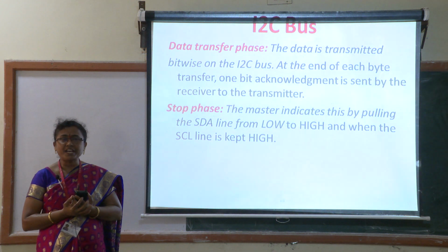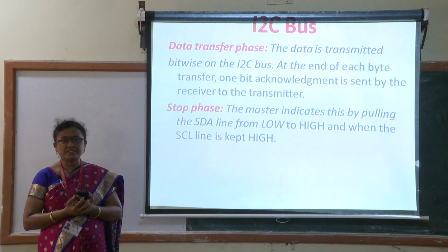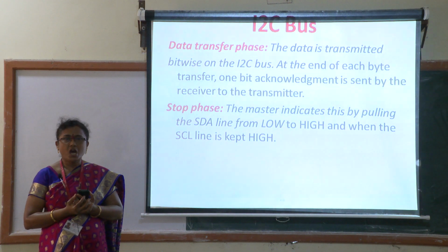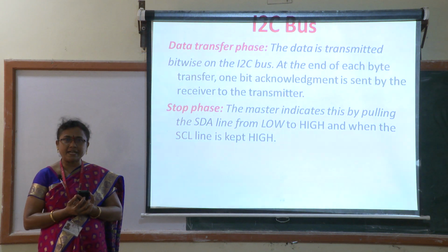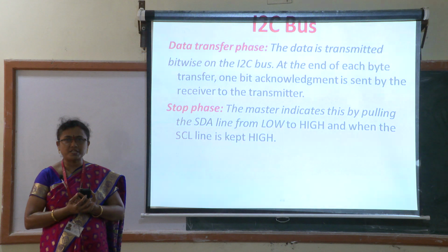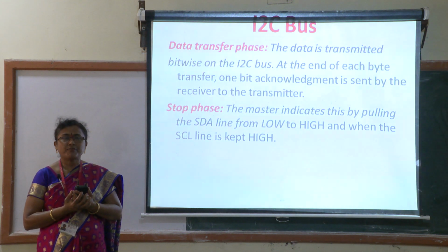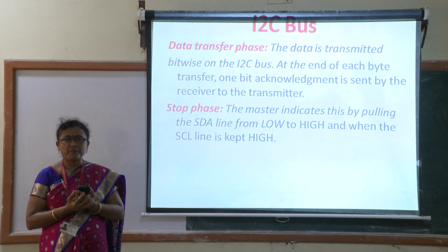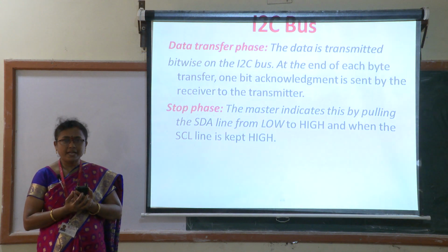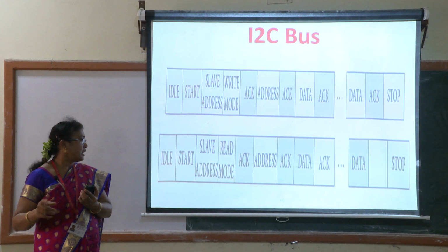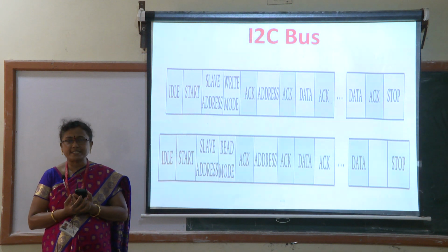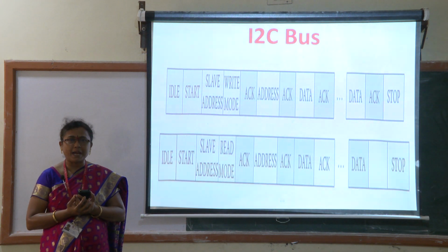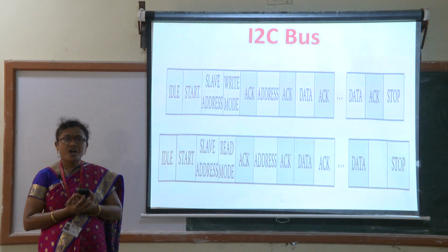These four frames will be common for any communication topology, whether it is I2C, USB, SPI, CAN, LIN, FlexRay, or MOST. Whatever you are using, there is a certain frame structure, and this is common. And this is the frame structure according to I2C. Under I2C, suppose there is no communication between the master and the slave or the slave and the master, then it is in idle mode.